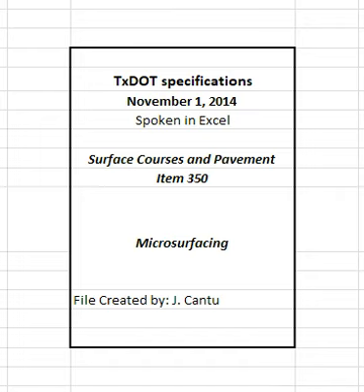4.3 Temporary Material Storage. 4.3.1 Aggregate storage. Stockpile materials to prevent segregation or contamination. Remix stockpiles with suitable equipment when necessary to eliminate segregation. Use a scalping screen to remove oversized material while transferring aggregates to the mixing machine. 4.3.2 Mineral filler storage. Store the mineral filler in a manner that will keep it dry and free from contamination. 4.3.3 Asphalt material storage. Keep asphalt materials free from contamination.